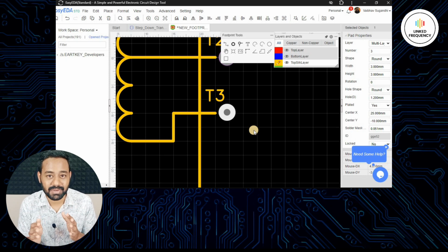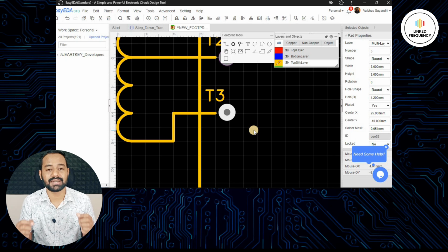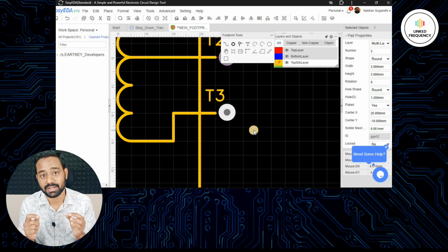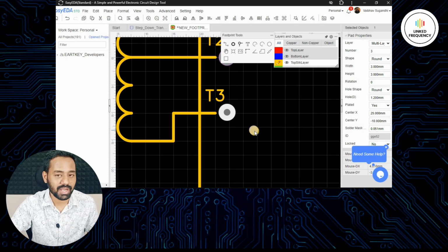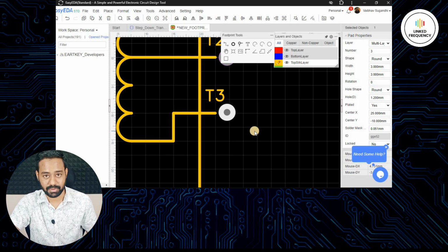However, this transformer pins, output pins are swappable. You can literally do that, but technically or logically, it is not right way to do it. That's why make sure that you give a proper pin number for the pads you're using on the PCB footprint.